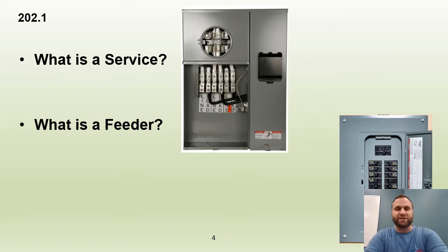What exactly is a service? Well, a service is exactly what that picture is next to us. That is the connecting point between utility and the premises wiring on any building. Service, by definition, in the NEC code book is just that. It is the connection and the equipment used to connect premises wiring to utility wiring.